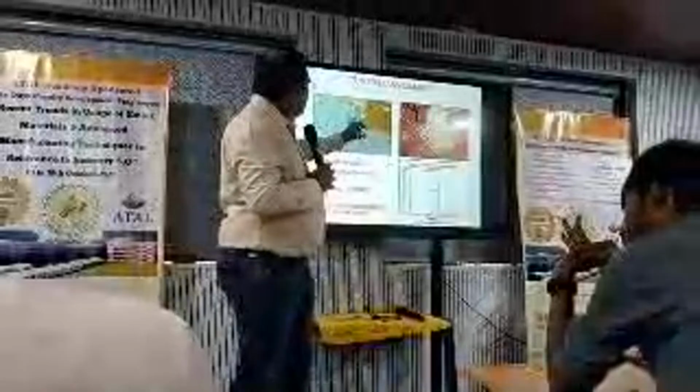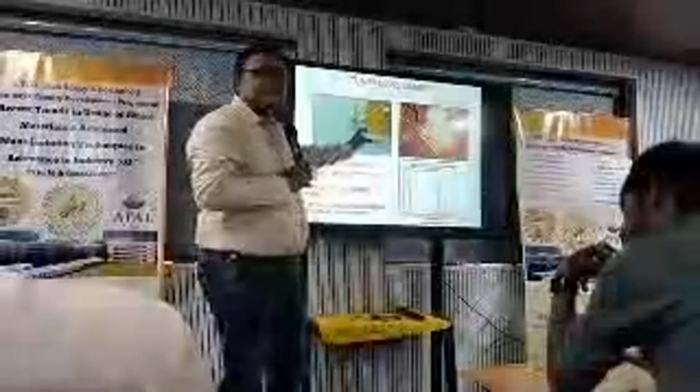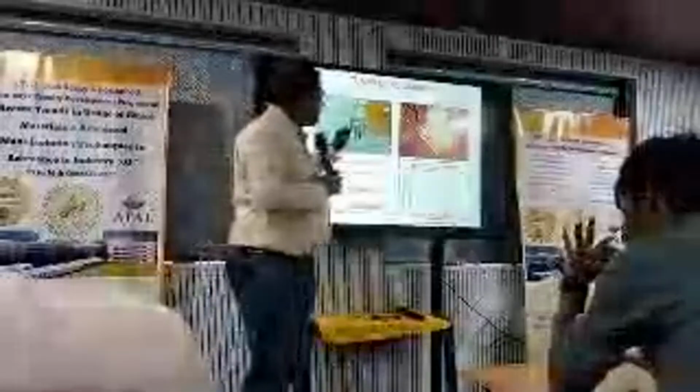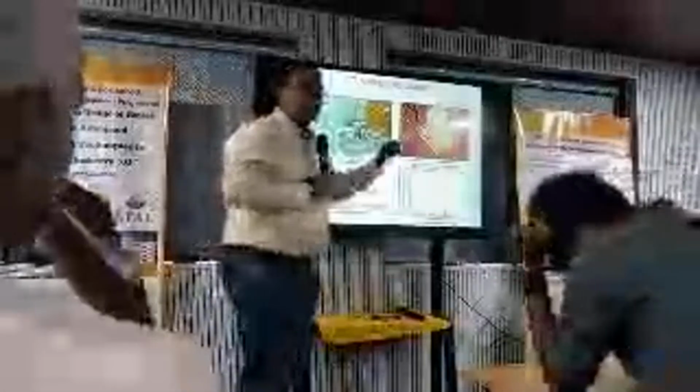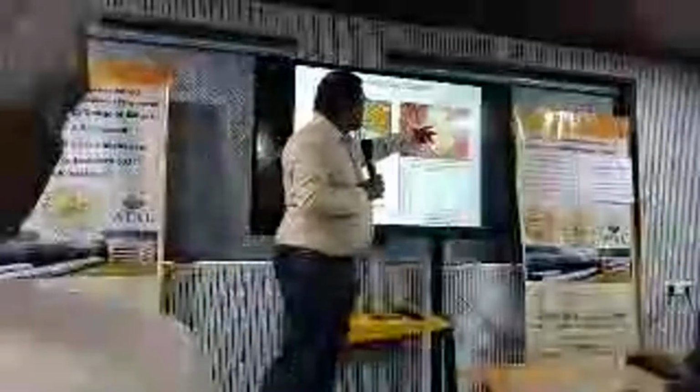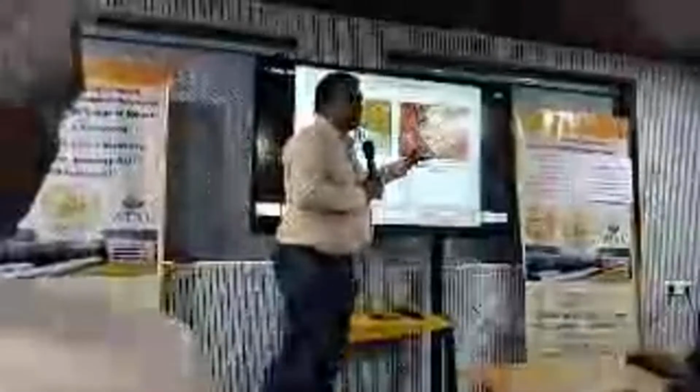So this is a tuned mass damper. It depends upon the stiffness as well as the mass of the system. You have to design the stiffness such that omega equals root k by m, such that the natural frequency of this material is equal to the natural frequency of the base material. Assuming it is vibrating at a certain energy, it has a certain natural frequency. If you create some equipment such that both natural frequencies match, then you have to assemble it at 4 locations.